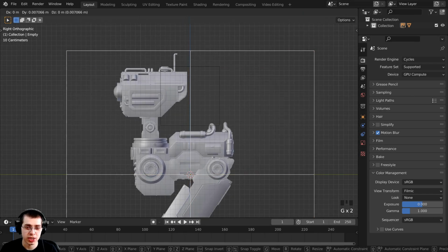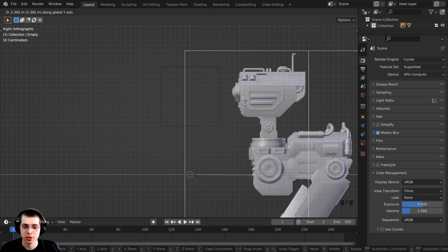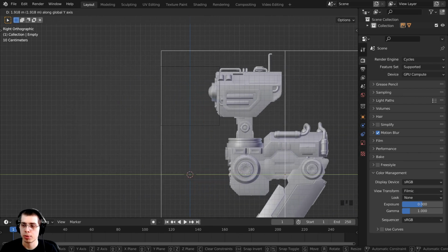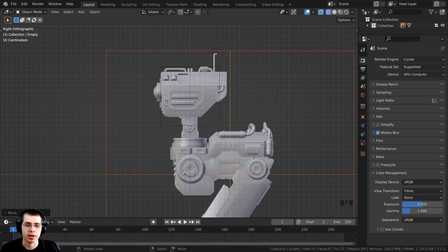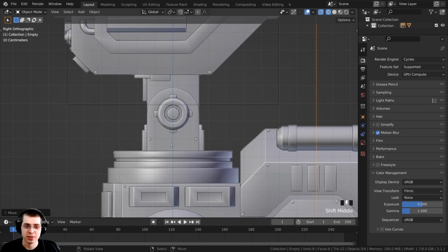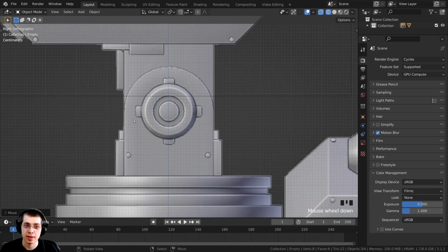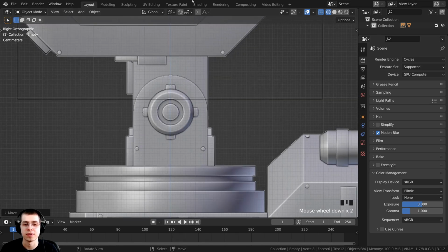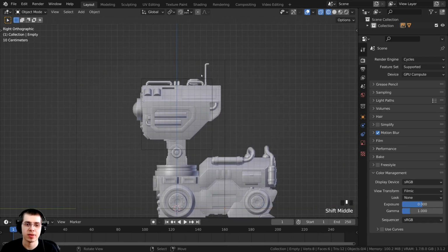So I'm going to press G to grab, and then you can click with your mouse wheel and then let go, and that is going to constrain it to an axis, and I want to bring it on the Y axis. And then I'm just going to bring this over and stick it right here. So if I zoom in, you can see there's this blue line, and the blue line is the Z axis going up and down. And so I want to bring the reference images so that the neck and the head are in the very center of the 3D scene. So I'm now going to press the A key to deselect everything, and I'm just going to select the cube.